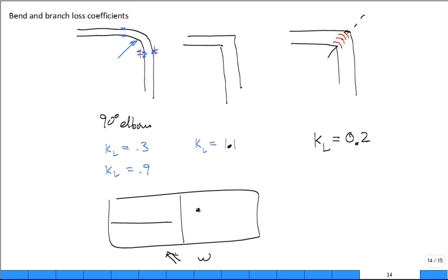And the air conditioning system was right here, and it came up to a main duct run that went down and fed the bedrooms, and then it had to transition and drop down, and so it went like this down to feed this one, and there was a kitchen over here, and it ran over here, and it did a mitered 90, and then it dropped down, and it fed the front living room. The front living room was always painfully hot, especially in 9 months of summer in the evening when you want to entertain guests in your living room, right?